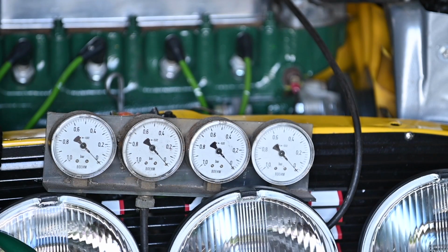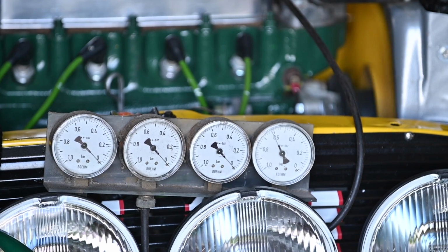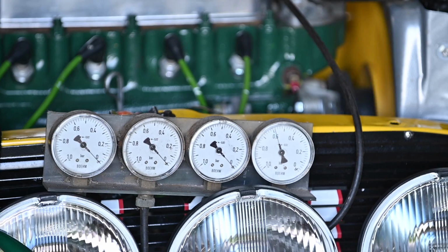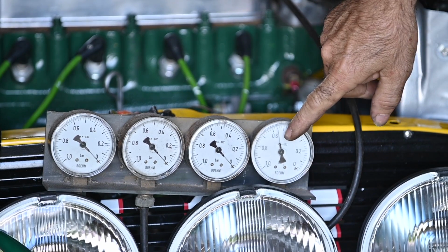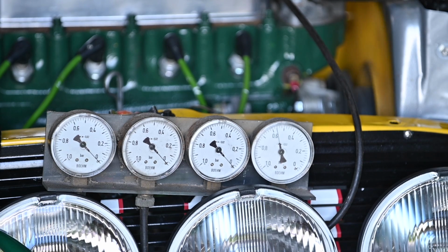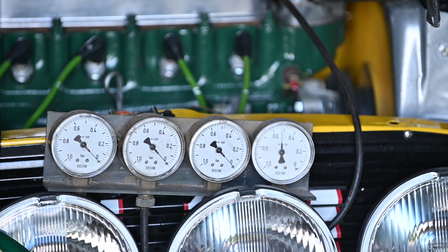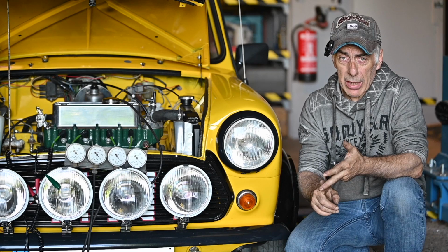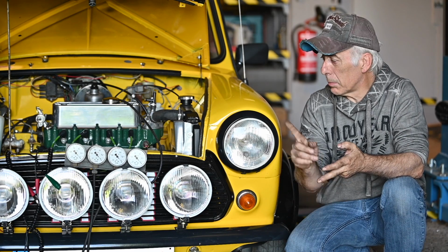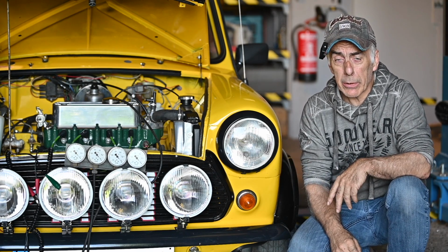I have hooked up the vacuum hose to the intake manifold, and now let's start the engine. And you actually see the vacuum being created. So that's the kind of vacuum we're going to use now for the distributor to advance it or not. So now that we know how the static advance is working and the dynamic advance is working, it's probably time to start some adjustment on this little Mini here.